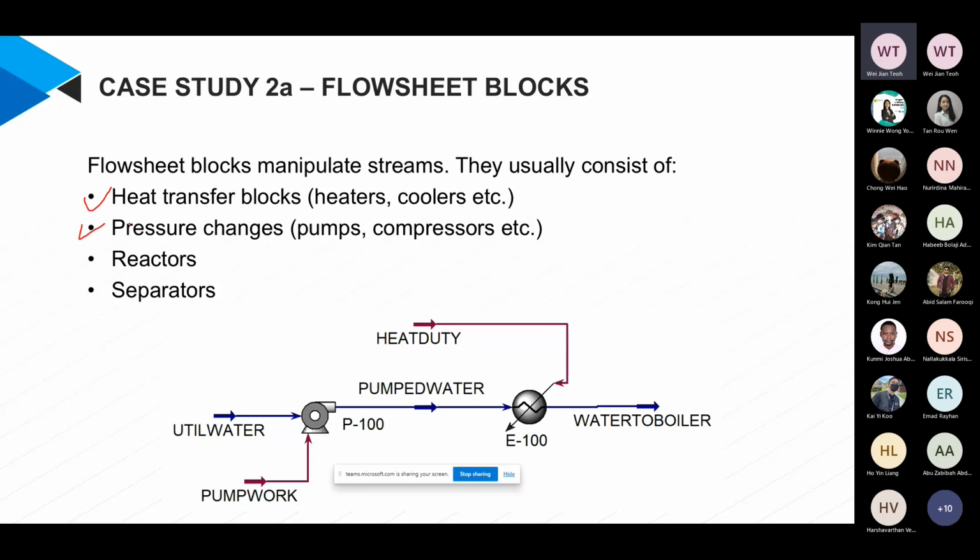I started with the simple ones, the pressure change, where you only need to give it the pressure change, which is the pump here. And you also have a heat transfer block where you need to give it the pressure difference. You also need to give the heat duty, right? So these two are very simple blocks that anyone can program. The next two are going to be tough because they require a lot of inputs. And we go for the easier one, which is the reactors.